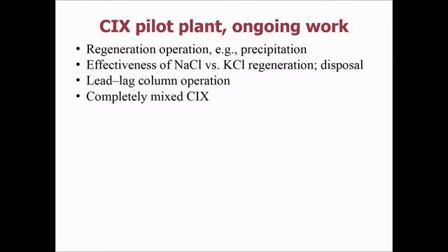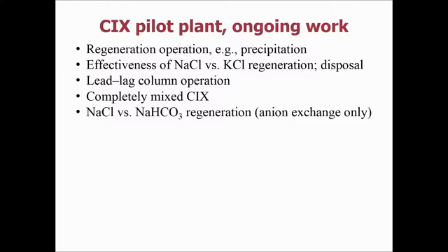We're also in the process of piloting a mini completely mixed combined ion exchange process that we'll be able to compare with the column results I showed. Just wanted to mention that as part of this piloting work, we're also comparing sodium chloride and sodium bicarbonate regeneration just for the anion exchange side.